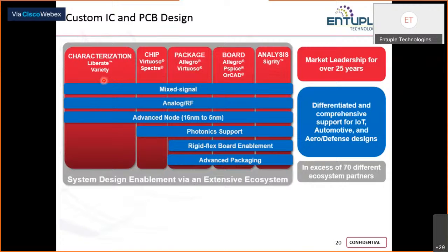Okay, and you will be having certain circuits that will be required to be made use of in a digital system, since you are talking about mixed signal design. So you'll be designing certain standard cells like an inverter, for example. You'll be designing an inverter of different drive strengths, an AND logic, flip flop. So digital circuits will be designed in Virtuoso, and you'll be developing the library files.